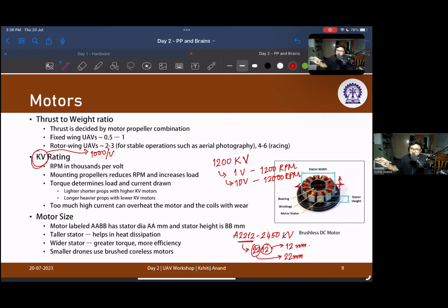But if you keep the same height and increase the width, you are going to be using more energy, though the efficiency is more or less going to remain the same. So it is going to dissipate a lot of heat. If you want to increase heat dissipation and make it cooler, then you make it taller.